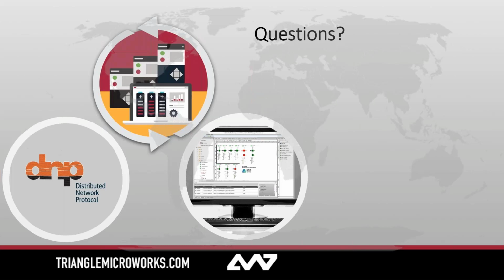Is it possible to work with real IEDs in the simulator? Oh yeah, so I should have mentioned this earlier on, but when you simulate a device inside of DTM, the external world has no idea that DTM even exists. It thinks there's an actual device sitting right there on your network. Meaning if you send out a GOOSE signal and you have another physical device inside your testing network that's subscribed to that GOOSE signal, it's going to see that.